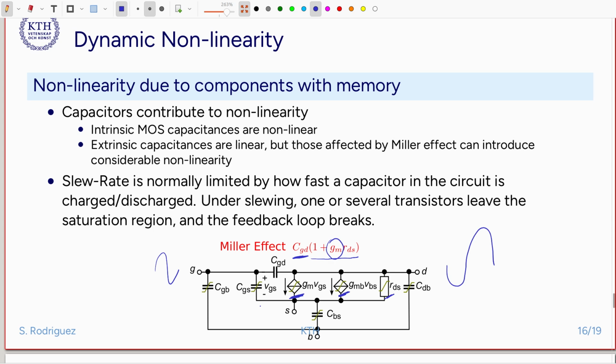So nonlinearity correction will decrease with frequency, because at higher frequency the loop gain is going to drop. So we will have to accept at some point that nonlinearities will rise at higher frequencies, and we will have to check them very carefully to see if they are within specifications.